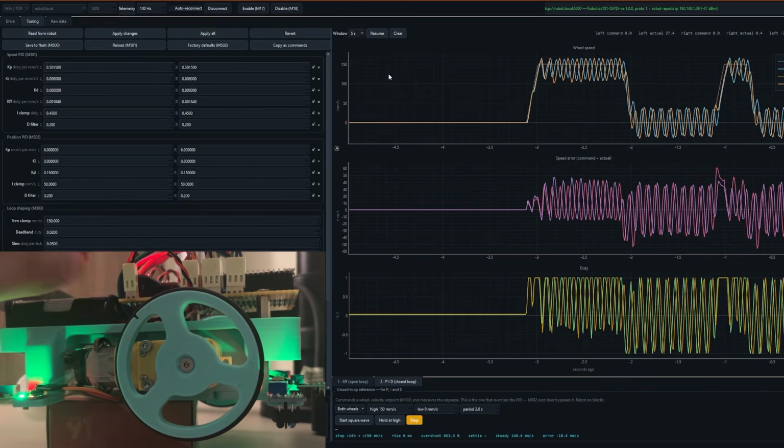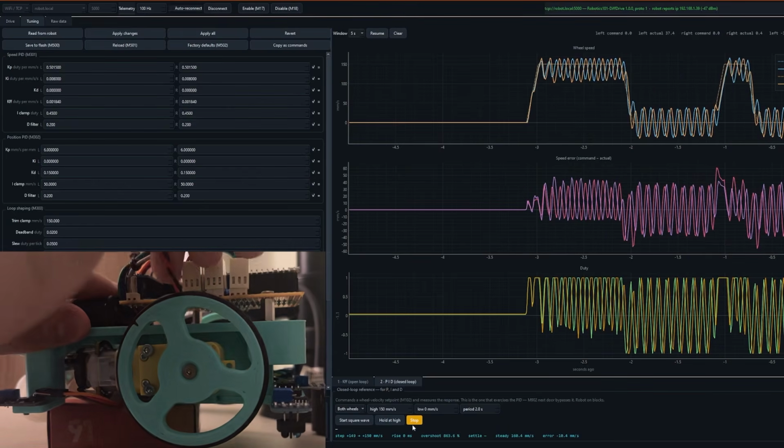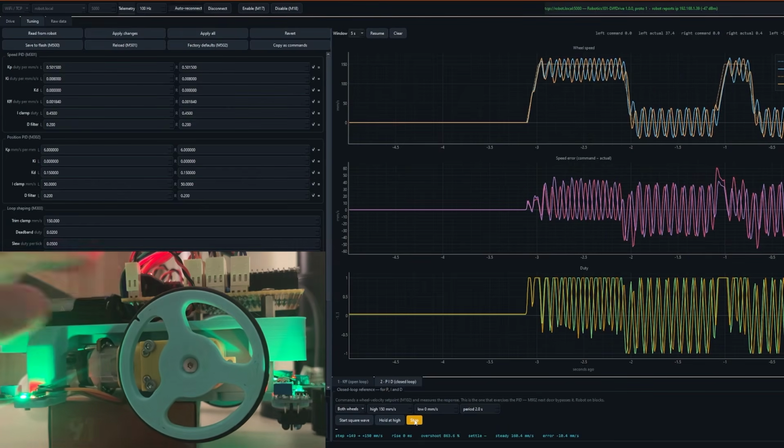Yeah, and the robot didn't even stop because it bugged out because of the high current. Let's power cycle it. But if you look at the graphs here, you can see how much it started to oscillate in both steady states. And that's the main reason why the robot actually crashed, because all of these are, just imagine a bunch of current spikes with the motors, and this is just running off of a few AA batteries, so they can't provide enough current fast enough. So let's reconnect to our robot and run this test again.